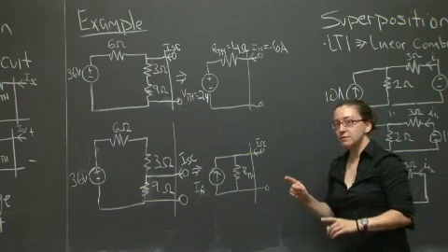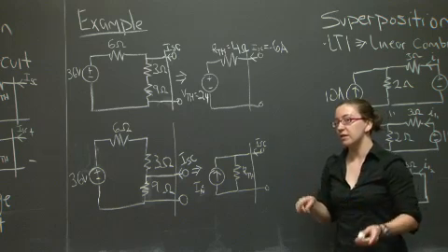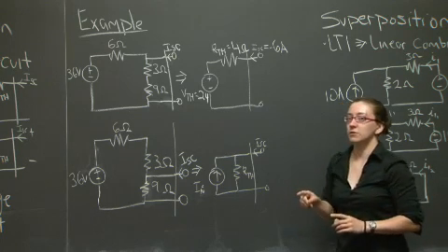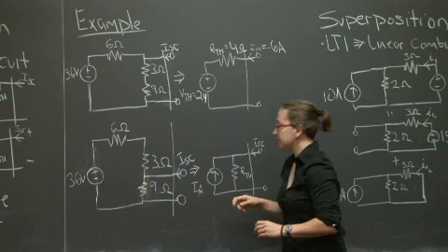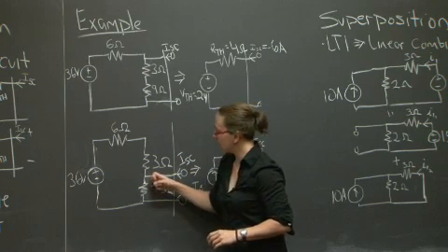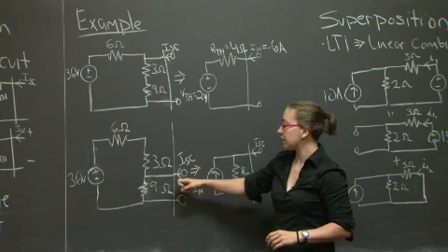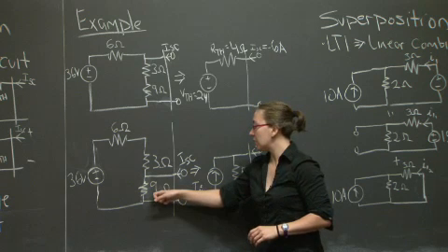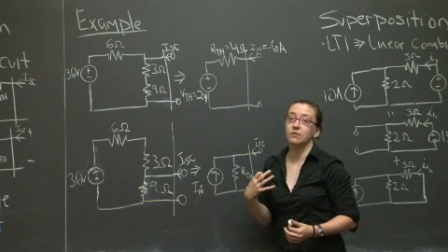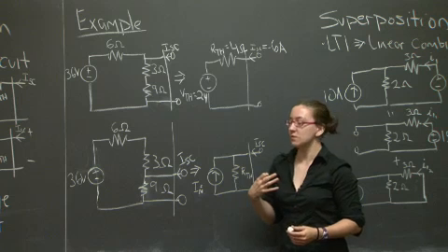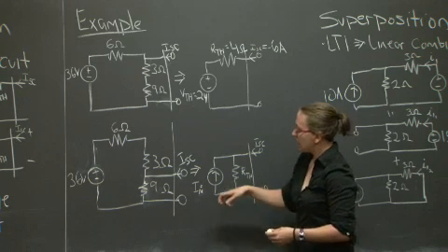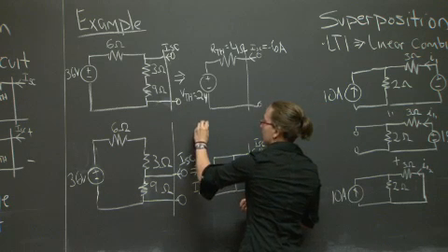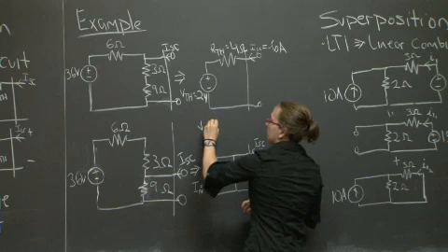Let's do it again, this time with a slightly different sample point, and find the Norton equivalent of our circuit. So if I'm only sampling across the 9 ohm resistor, I personally still solve for the Thevenin equivalent voltage first because I think it's easiest. I'll just make note of it over here.